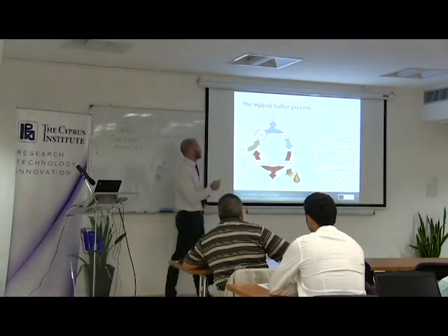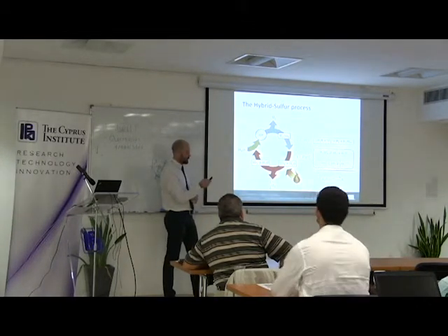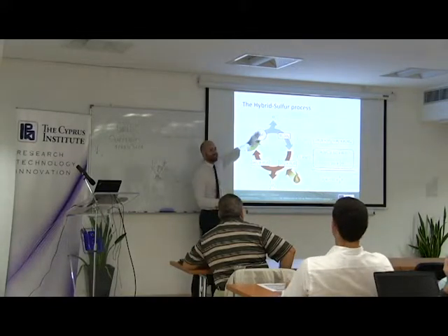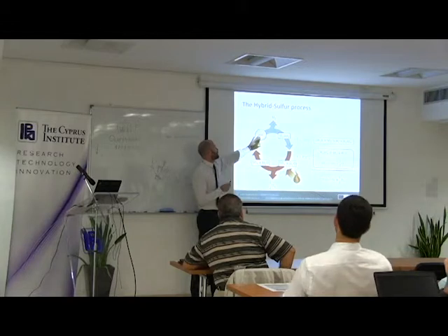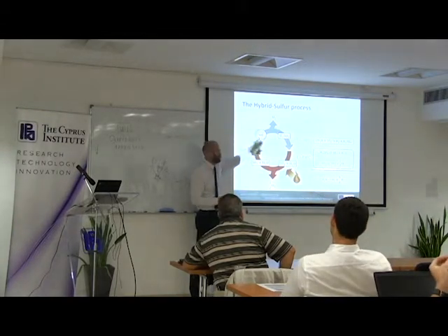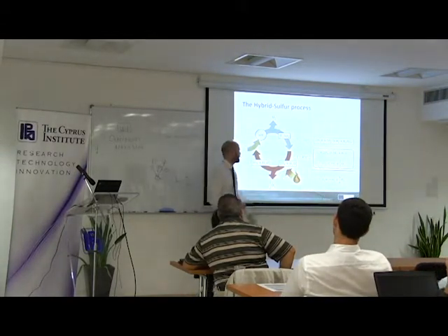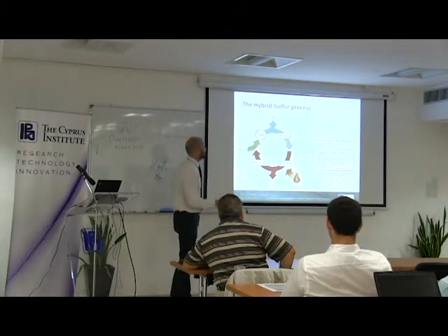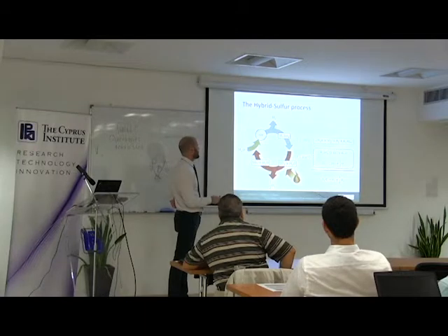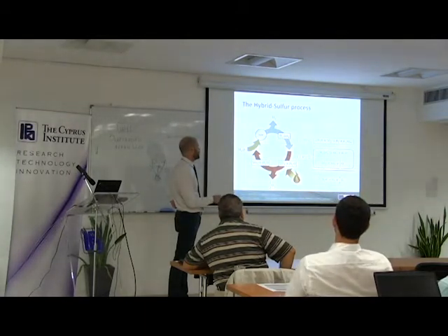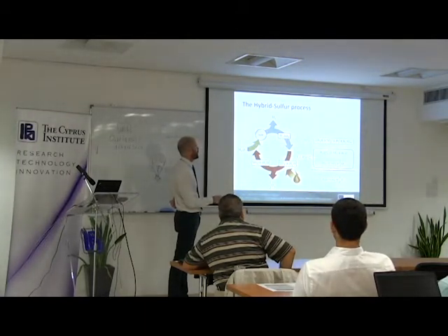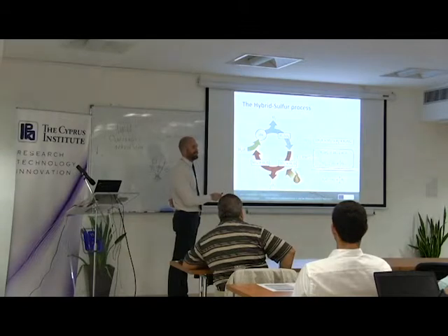The hybrid sulfur is called hybrid because it uses electricity. Okay, here there should be a thunderbolt going here to say that this step in the hybrid sulfur process is carried out with electricity, while the high temperature step is carried out with heat. Here you find the reaction. You see that water reacts with sulfur dioxide and another molecule of water. So you have two molecules of water, one of sulfur dioxide. You produce hydrogen, which is the product, and sulfuric acid.